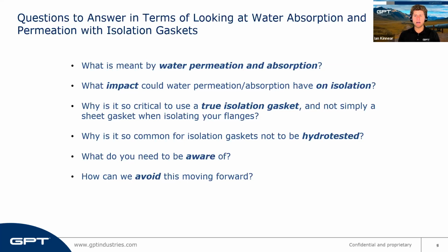So in line with this, it's giving criticality to a true isolation gasket and not using a sheet gasket, and some of the reasons why in conjunction with the sleeves and washers. I'm also going to talk about hydro testing isolation gaskets. Not doing this is a common practice, and it's a direct result of these. And this is another headache isolation gaskets can provide. And there are some solutions, and I want to talk through it.